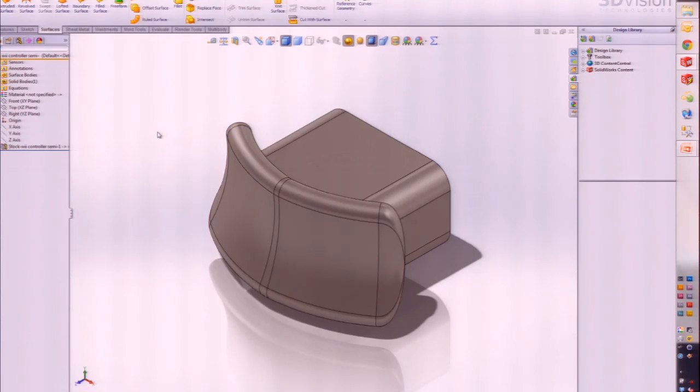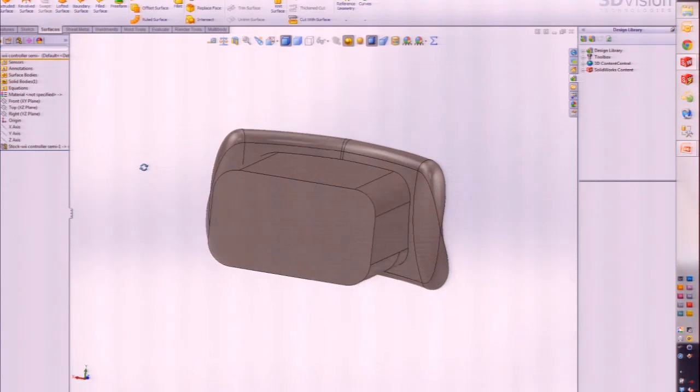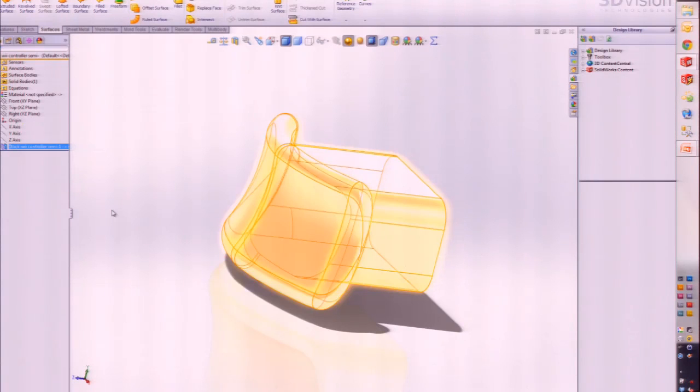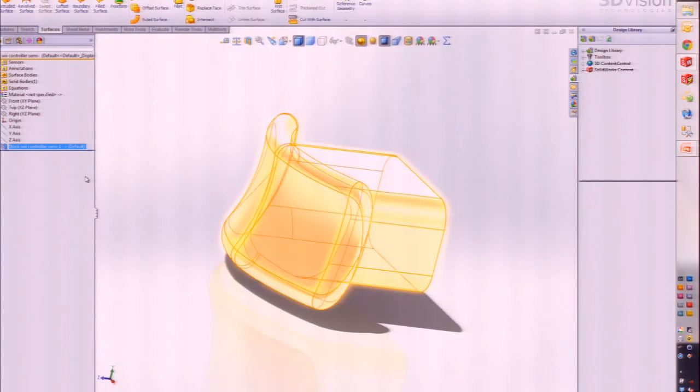What this allows me to do is have an individual part file that's completely dependent on the other part file, the master model. If you have ever worked with in-context assembly designs, you know that this little arrow represents an external reference. Question back there?